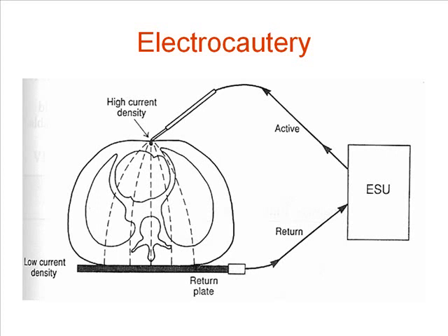And you could try altering your rearrangements. The practical thing is just to unplug it and see what happens, because it may have been the biggest piece of equipment responsible. But it may be that another previous piece of equipment, as you correctly state, provided the bulk of the leakage current, and the last piece was just the last straw.